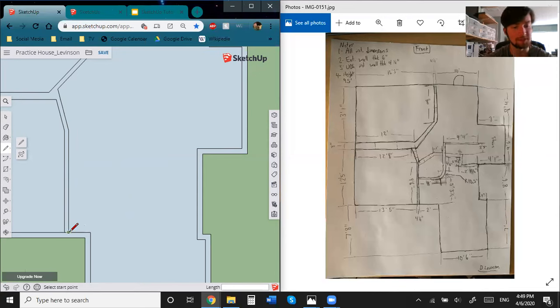Wow, okay, so I'm gonna have to do it again. Up 5 feet, 3.5 inches, 5 feet, 3 space 1/2 inches, enter, and then I'm gonna find that endpoint. There it is. Go to the right 3 feet, enter. Good.